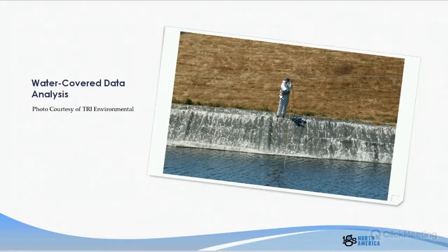So the biggest problem with this method for the deeply filled ponds is getting really good accuracy in leak location. For one thing, it's hard to tell exactly where your dipole is along that cable. And for the other thing, it's really hard to say where the peak is coming from when you're just passing the dipole back and forth, and it's really hard to maneuver left and right back and forth.